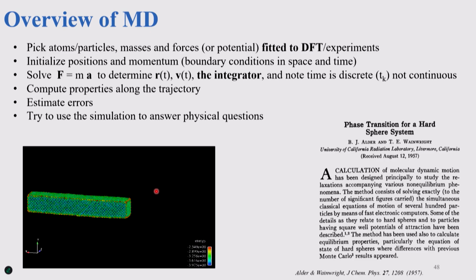Nothing works. So in an MD simulation, again, you need initial atoms and initial masses of the atoms. The forces are initially zero, there are no forces at first, and then you assign the momentum and boundary conditions, so that if you have a chunk of aluminum, you are pushing it. After the atoms leave one side, they come back and wrap around. This is called periodic boundary conditions, where instead of modeling an infinite system, you model a certain repeat unit, which after a certain point comes back from right to left, or left to right.